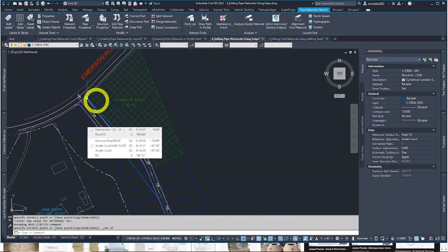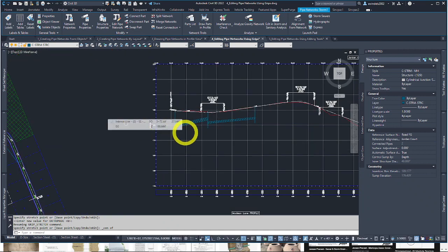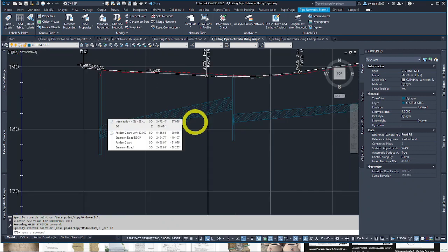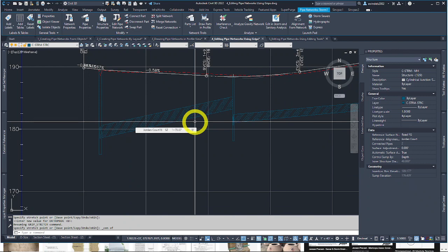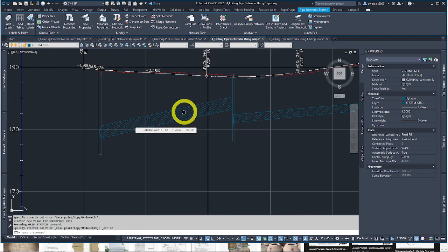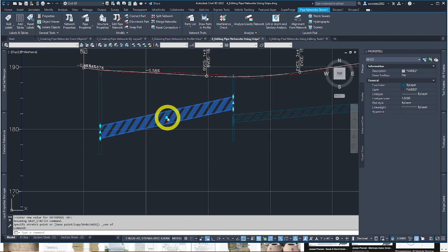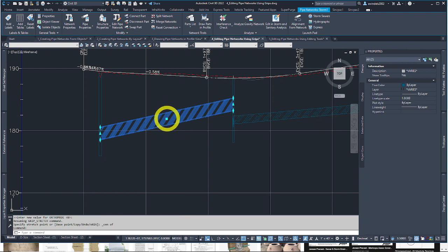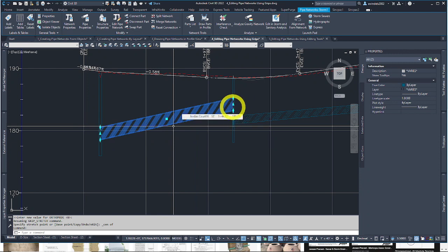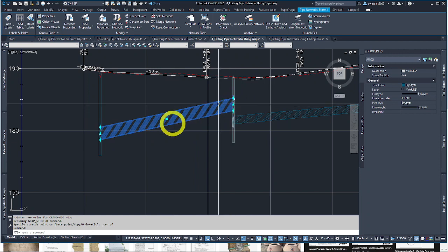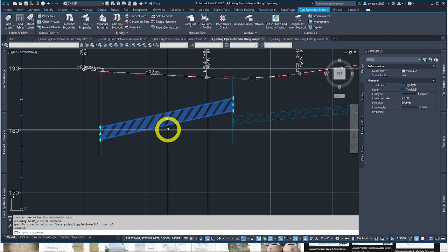Now it wants us to do a quick little edit in the profile view of the same pipes. We'll go over here. It says grab the pipe furthest to the left, so that would be this big one. And we're looking at the different grips. Remember, this moves its elevation without changing its slope, so it keeps the same angle. These ones move it in the elevation sense and change its slope, basically, to say it quickest.